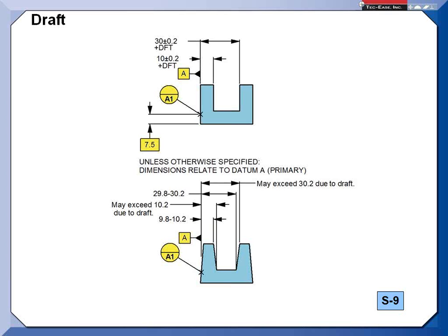No, I was just thinking of the angle that results from the draft if it's oriented towards a parting line, essentially, because it appears you're trying to facilitate the extraction of the part from the mold. Correct. That's what the draft's all about. And if it's going towards the parting line, or the orientation's tied into the parting line, it might be a nice definition, but that may not suit. I can see where this would get real confusing real fast. And that's why we created a bunch of figures to help explain.